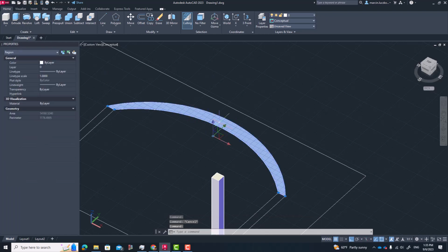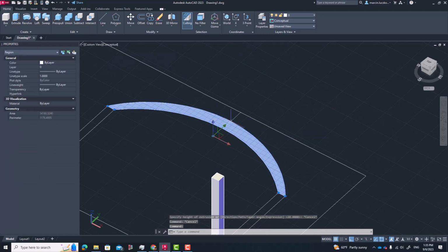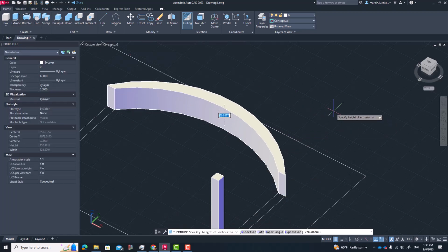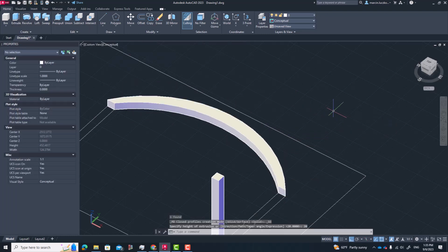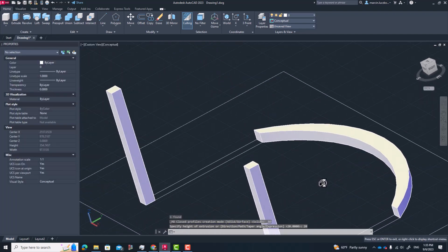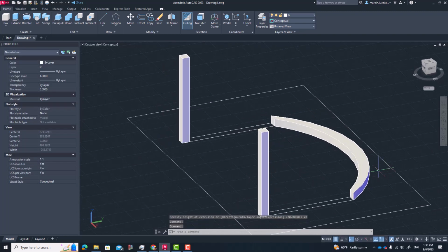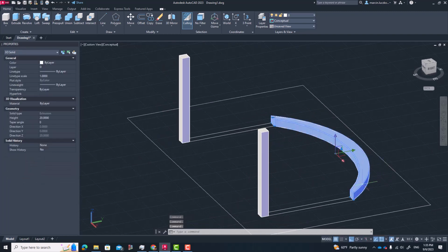Right now, this region, it's something like a surface, so it should be possible to extrude it. Let's try. If I will click extrude, so I first mark the object, then I click extrude. I can specify now 20, so I have extrusion of this object with 20 centimeters. So again, this is something which worked. It creates a 3D object. Right now I will click on it.